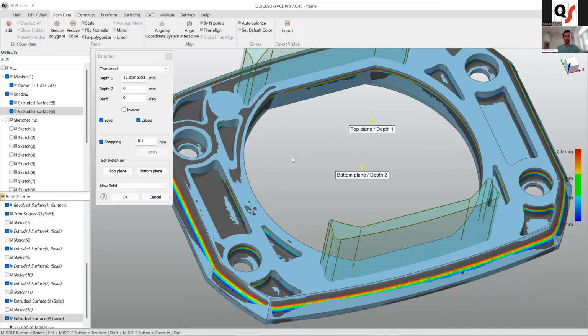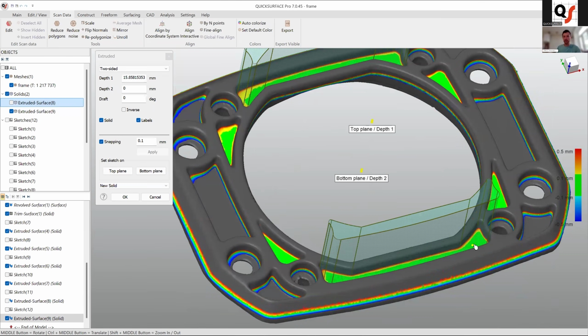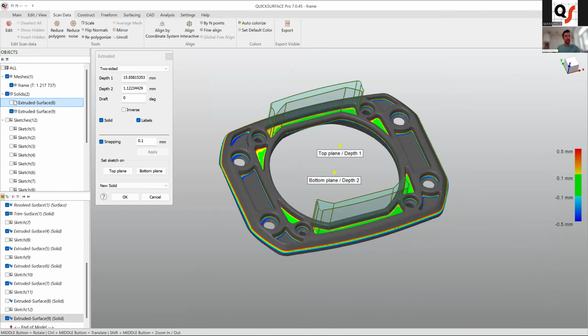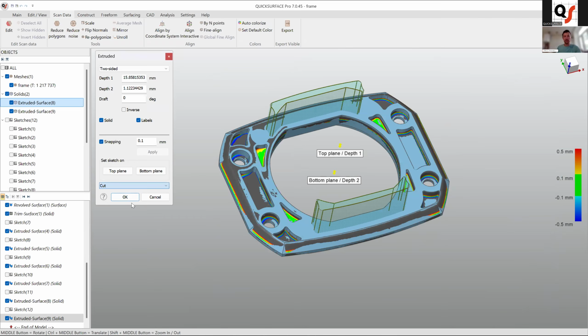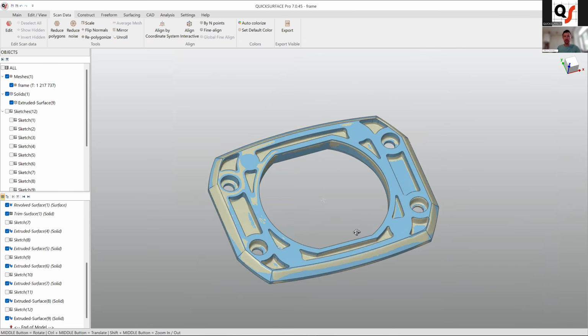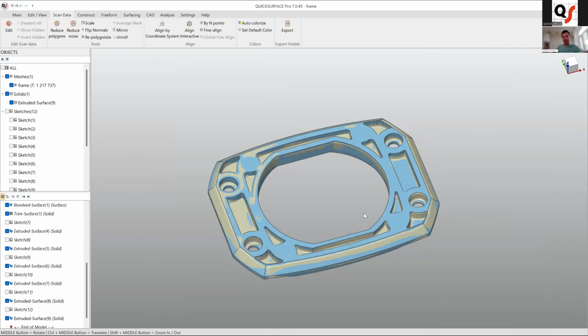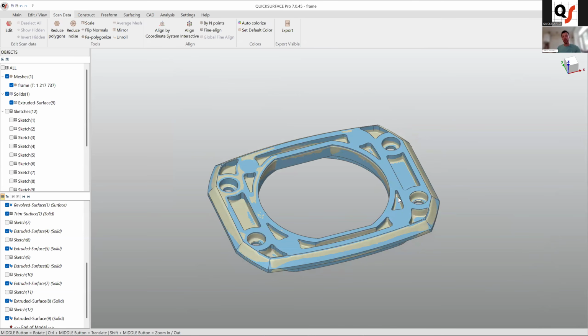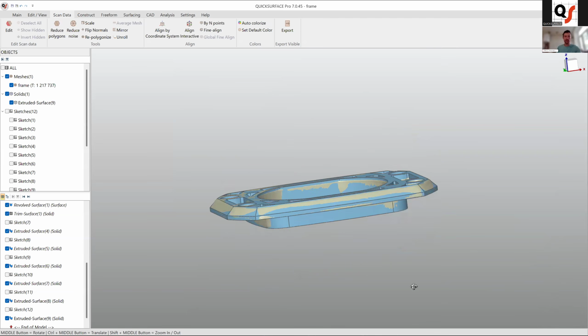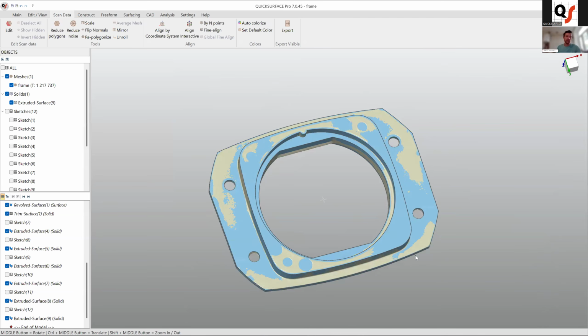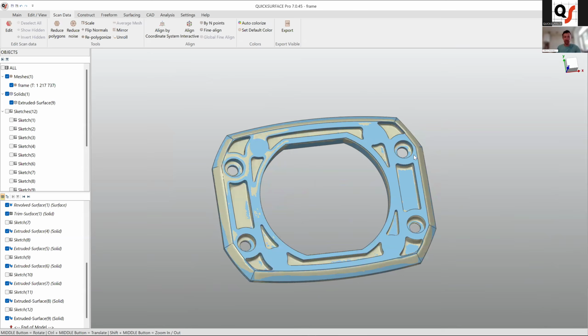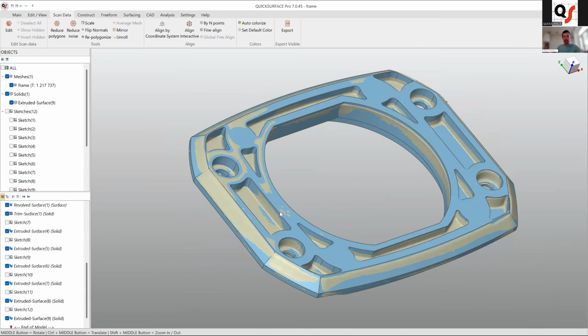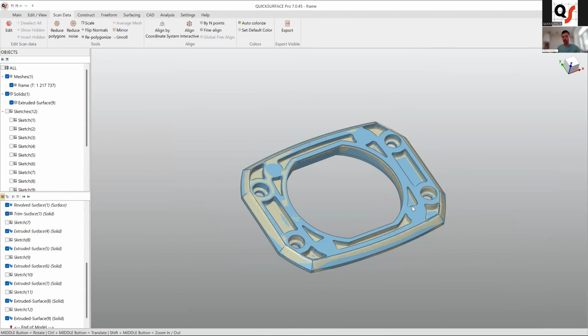Of course, again, back to the same operation, extrude. Let's snap it. Bring back the solid, cut. Okay. And this way, basically, this part is why I said it's simple, because all the actions are repeating. Here and there and again, sketch, extrude, cut, sketch, extrude, cut, sketch, extrude, cut. So this is the beautiful part of some mechanical parts. You just have to find the correct place from where you can create a sketch and just proceed with it.